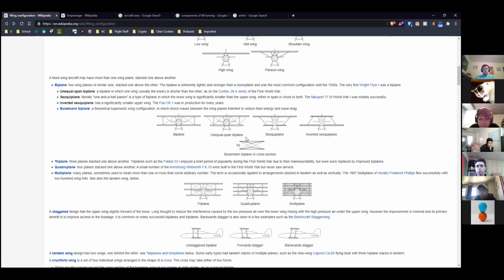So all biplanes are basically really slow. These wires they're using to brace it were fine when your top speed in any plane was like 40 miles an hour. But as you will learn eventually, a wire is just a really long thin cylinder, and a cylinder is the draggiest possible shape. So we try to avoid those when possible.